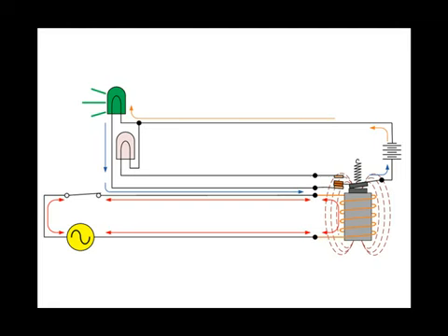I've never seen a relay without a normally open set of contacts, but I have seen many without normally closed contacts. Normally closed contacts were added to allow using the off state of the relay to control other actions. The components of a relay that are of interest to the control system are the coil, the normally closed contacts, and the normally open contacts.